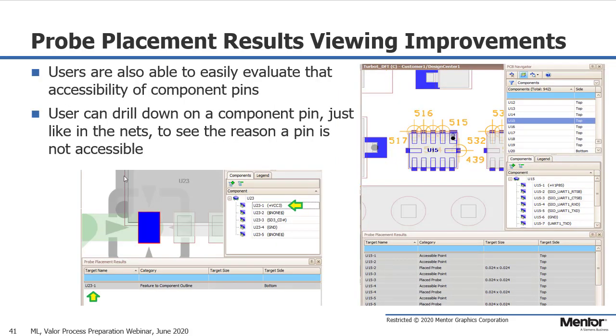A number of ways are available to review DFT results. Graphically, click on a pin or via and the specific results for that feature will be displayed. In component or net mode of the PCB Navigator, click on pins, vias, or nets. Use the built-in filtering to further reduce nets that have many connections to focus down to the connections that are of interest.